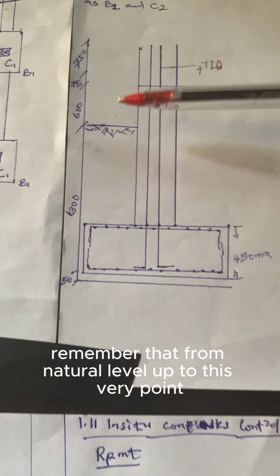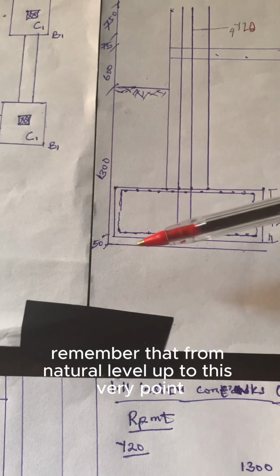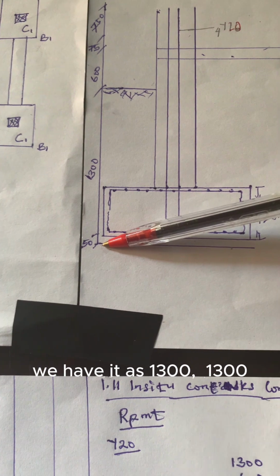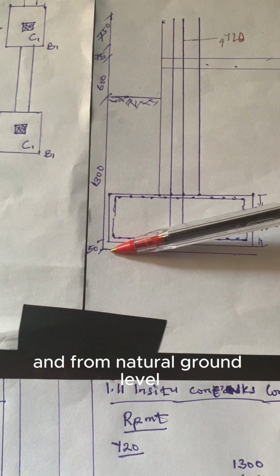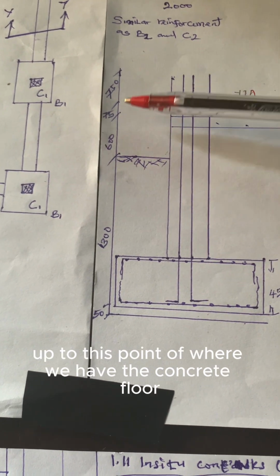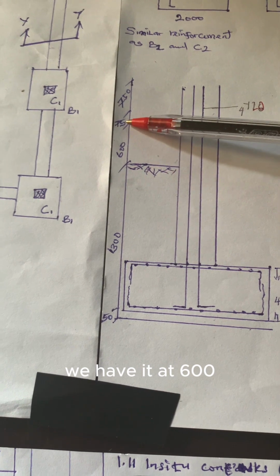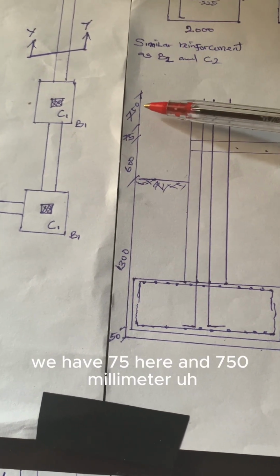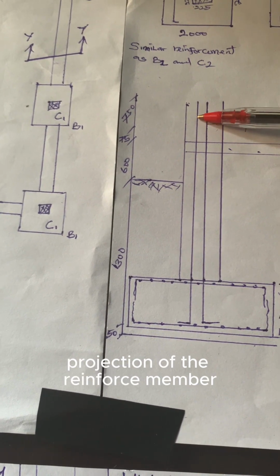Remember that from natural ground level up to this very point, we have it as 1003, and from natural ground level up to this point of where we have the concrete slab, we have it at 600, and we have 75 here and 750 millimeter projection of the reinforcement bar.